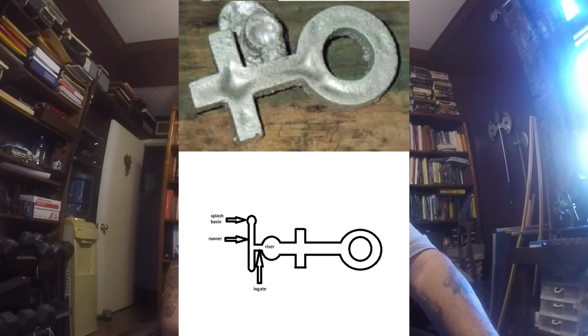Anyway, in addition, as you can see, in between, where they introduced the metal, it went directly into the mold cavity. There weren't any runners. All they had was a huge down sprue, which apparently I'm thinking that what they meant was that they were going to use a riser as both the sprue and the riser.